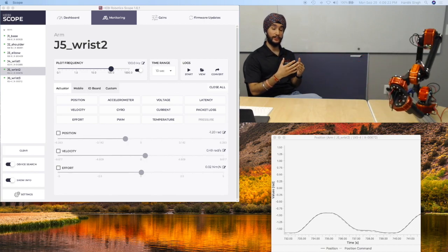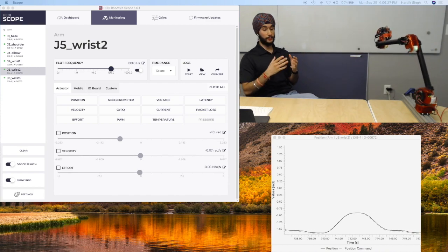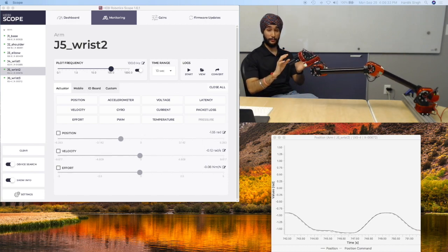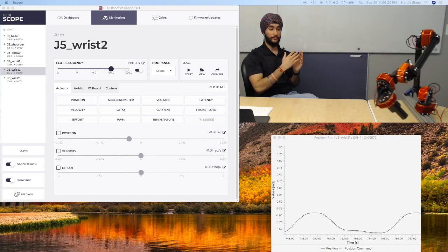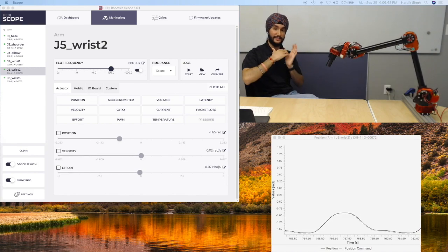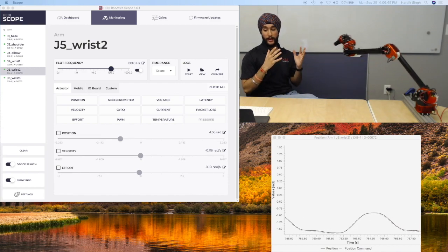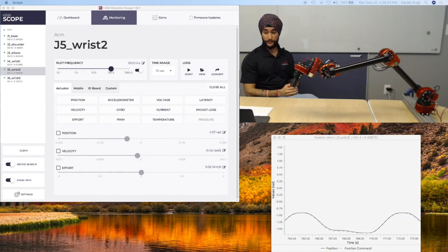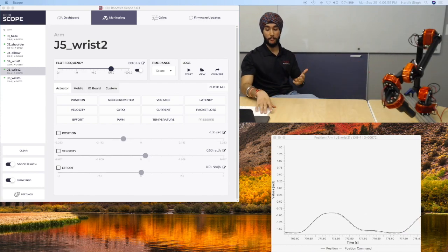And in this case, what we're doing is we're commanding minimum jerk trajectories, where jerk is actually the time derivative of acceleration. So in this case, the trajectory matches velocity and acceleration constraints at the end of each waypoint. And so it prevents the arm from jerking into any position. And it really gives it a smoother profile, sliding into each position, sliding out of each waypoint. At the end of the day, the better your input that is used to create the trajectory, the better your trajectory will be. But doing trajectories all around the arm really allows you to make the most of your motion control.